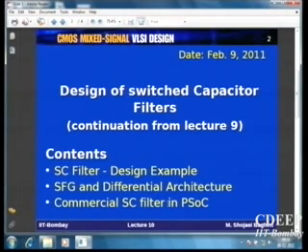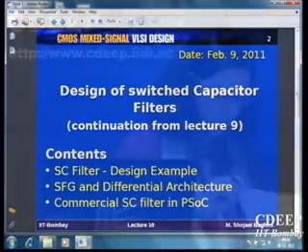A recorded version of this lecture will be given here on Friday. Eventually, what is important for you to know is the required characteristics in Z domain for the design. If you know that, then the remaining part will be straightforward. You don't even need to know the corresponding filter in S domain, because knowing the corresponding filter in continuous time domain will be of no use. Practically, it's enough to know the characteristic of the filter in Z domain.